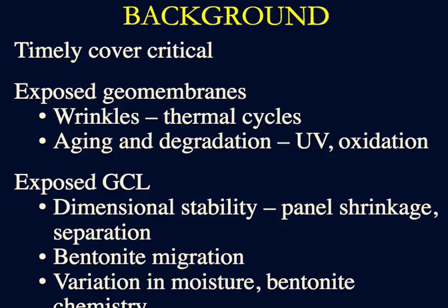The main problems for exposed GCLs include dimensional stability, resulting in shrinkage of individual GCL panels, separation along seams, and formation of gaps between the panels, migration of bentonite, uneven bentonite concentration in the GCL installed at a site, and variation in moisture content of the GCL and the chemistry of the bentonite component of the GCL.